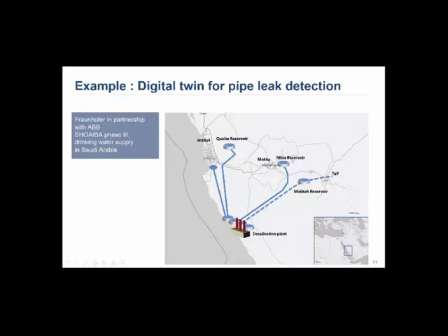This system is represented by a digital model that calculates the measurement metrics at certain key points based on the temperature, flow rates, and reservoir levels. By looking at real-time measurements at these same monitoring points and comparing this to the model, leaks can be detected, the performance of the system can be managed, and faults can be localized.